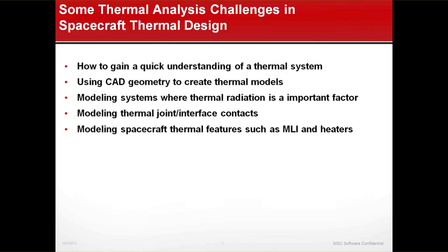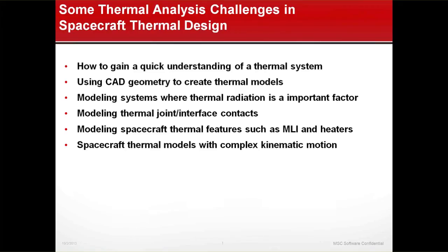MLI and heaters and some thermal features such as those are not always easy to add in software, so we've tried to make that easy, and I'll show you examples of that later. Modeling complex kinematic motion: a lot of spacecraft have doors that open and close and solar panels that unfold and articulate, and we have some very powerful kinematic modeling features.